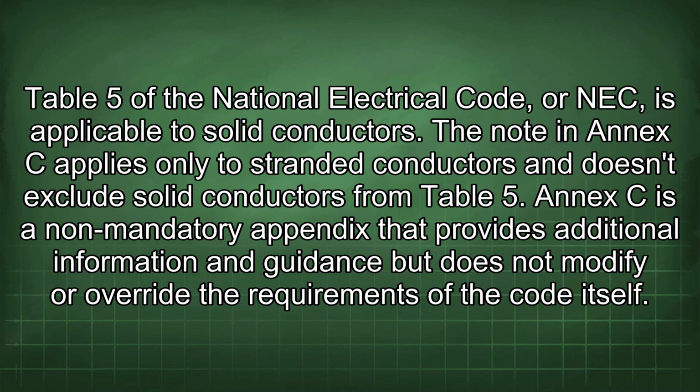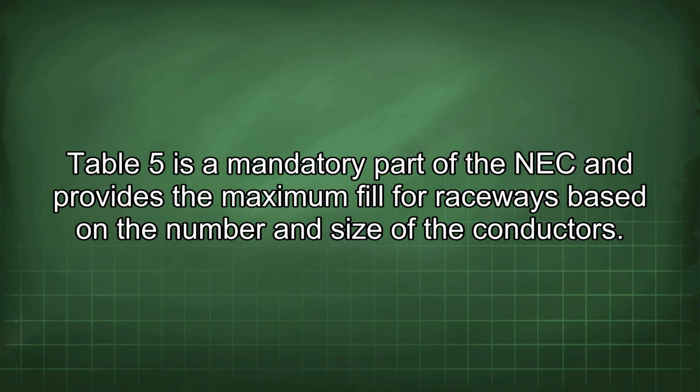Table 5 of the National Electrical Code, or NEC, is applicable to solid conductors. The note in Annex C applies only to stranded conductors and doesn't exclude solid conductors from Table 5. Annex C is a non-mandatory appendix that provides additional information and guidance but does not modify or override the requirements of the code itself. Table 5 is a mandatory part of the NEC and provides the maximum fill for raceways